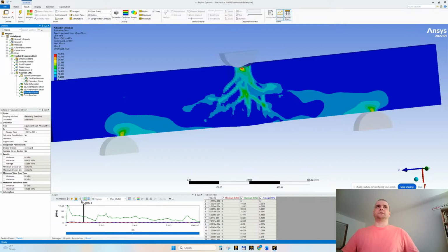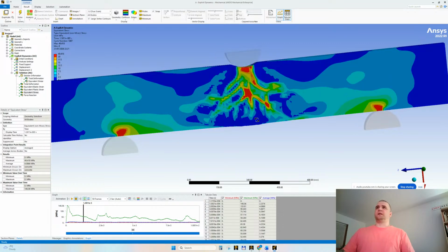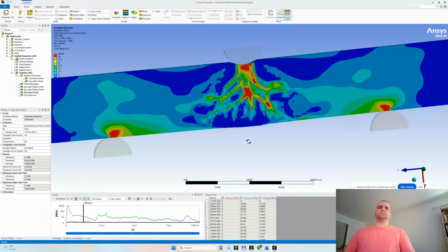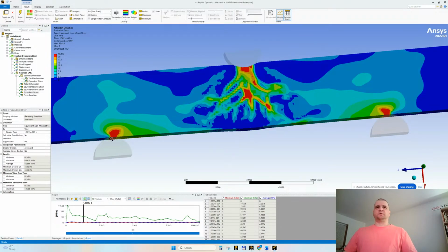So for example, if I would like, let's not say cheat, but if I would like in static and transient to show some kind of mesh erosion, because for example, I know that at 20 megapascals the material breaks, let's suppose, then we can go here on geometry and choose capped surfaces, and it will hide the elements which meet this condition.